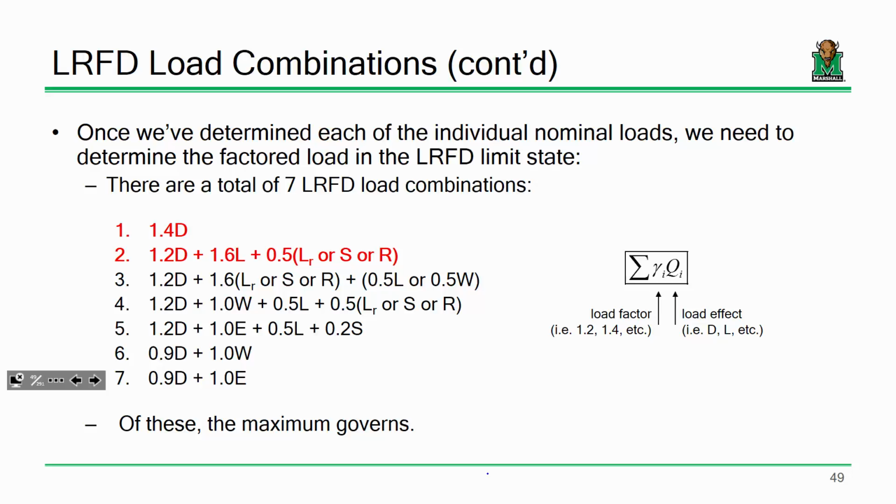That's not how we assess design considerations in both steel and concrete. What we do is we take each of those load components and we combine them into the following load combinations. These load combinations are derived from all that probability and statistics stuff that we looked at earlier in order to try and address uncertainty and maintain a uniform level of safety.